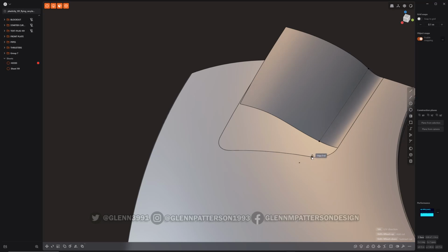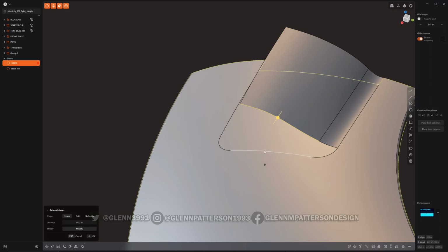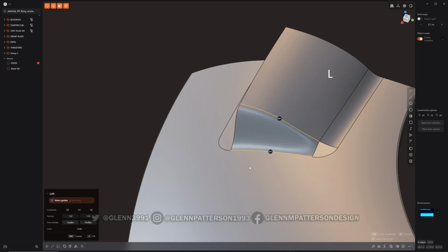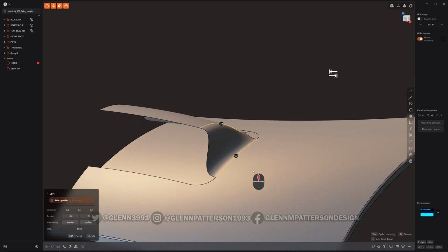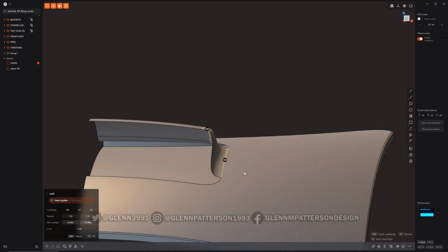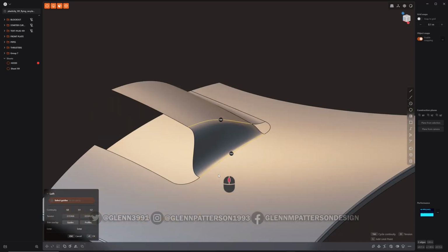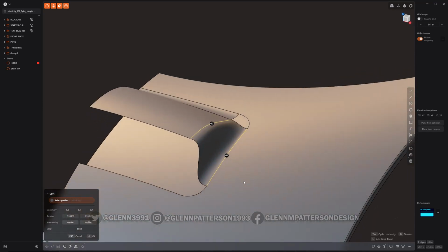Well, I could just use this snap right here at the end of the curve. Boom. Now it should nicely go across there. And there we go. And we can even do a G2 if we wanted. You can change the tension to make it really obnoxious, but we're going to kind of back it off a little bit. It's whatever shape you're hunting for there.